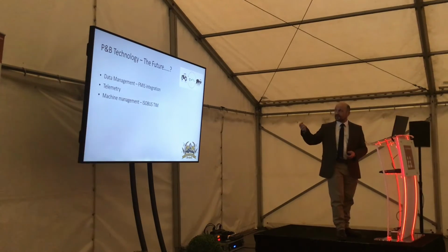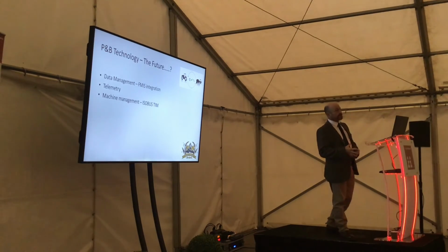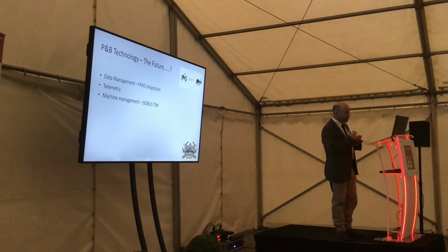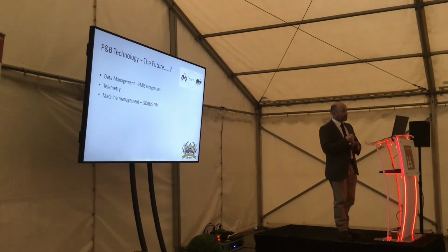You'll see more and more of this. But this is where the implement can actually manage aspects of the tractor. So you can have things like balers and other harvesting machines that can actually tell the tractor how fast we want to drive in these crop conditions to get optimum output, so optimum quality of work. And I need oil now from this service to do this job, so that the implement can actually start to control the tractor rather than the other way around.